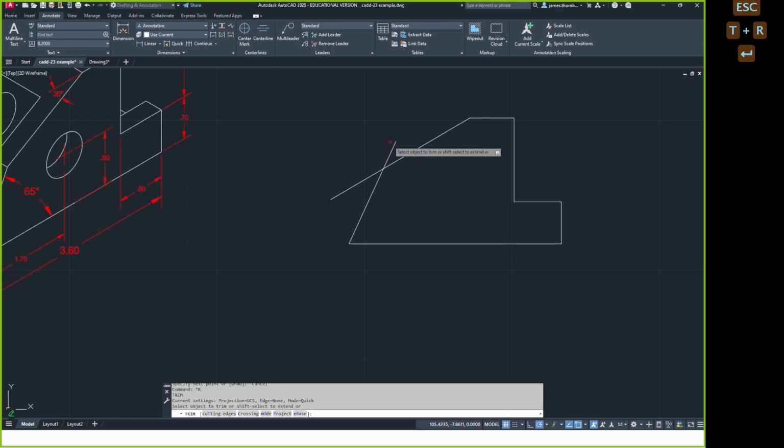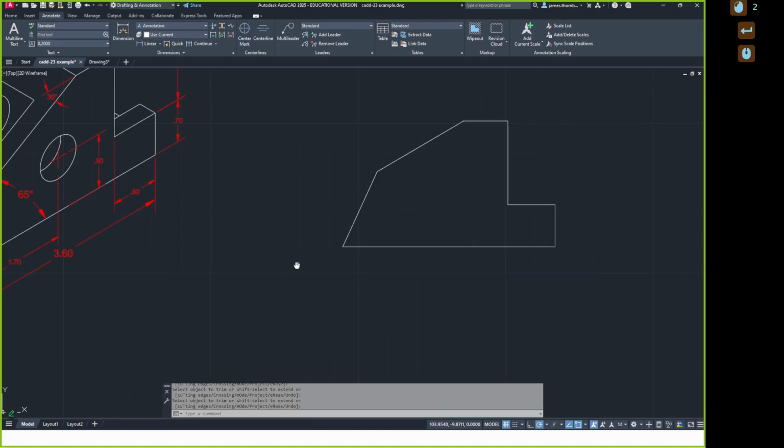And now I can trim off those two things. Okay? So using that tab to set that angle lets me do it. Or I could have used polar and just said, less than 65, or the distance, so less than 5 angle 65, just made some random length line. But I like the tab way better.